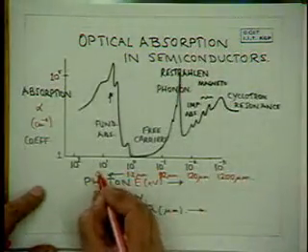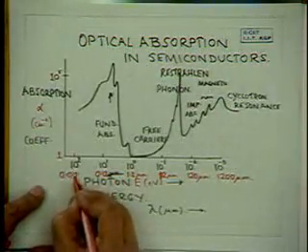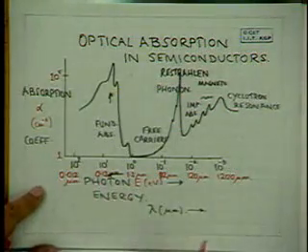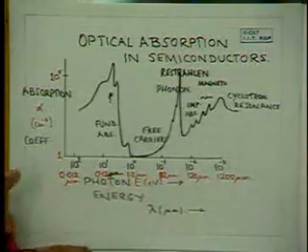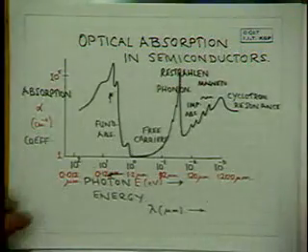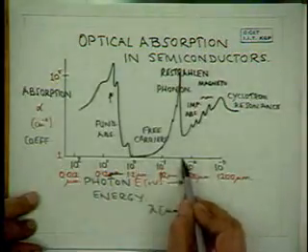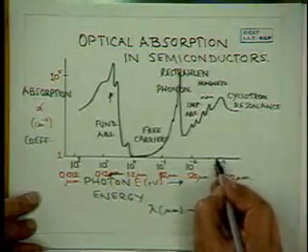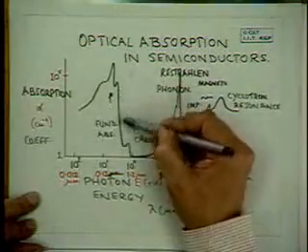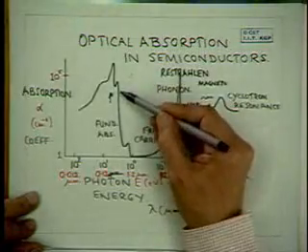And here, this is 0.12 microns in the UV, and this is 0.012 microns in the far UV. So this energy axis scans a large wavelength region right from the UV to the visible, into the infrared and the far infrared. And so far we have only discussed this fundamental absorption that occurs due to excitation of electrons from the valence band into the conduction band.